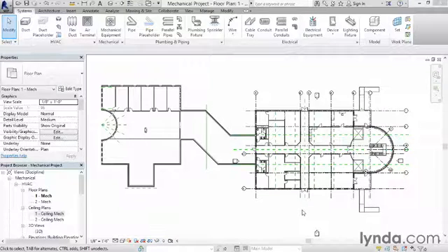The components of this video will include choosing a VAV unit, then finding the proper place to put it, and the correct elevation above the ceiling. We'll then cut a section to make sure it's in the correct place.